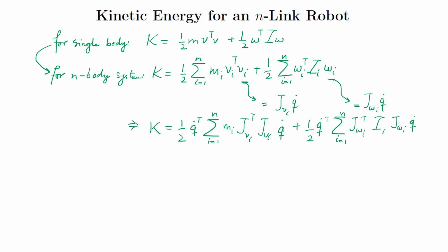All right, now in this particular case, you can also register that this inertia tensor, we have already defined, is going to be equal to, when you use the rotation matrix, with the same subscript i over there, and then you can use the inertia matrix I, which is fixed. You can compute it once and use it again and again, and then you have rotation inverse or rotation transpose because it is the special orthogonal matrix.